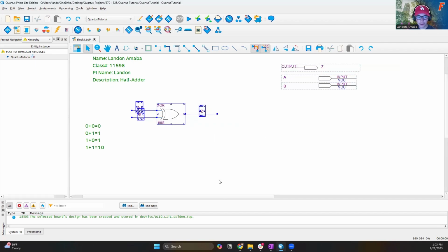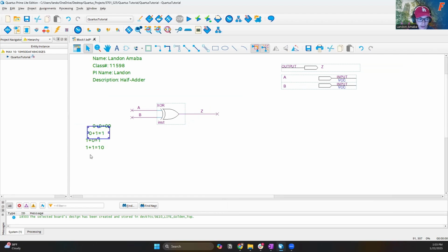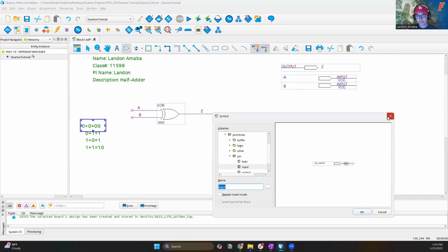We have our exclusive OR gate. This will handle the first 3 operations, 0 0, 0 1, and 1 0. But then how do we specify that there's going to be a carry here? In all these other examples, this is really 0 0. This is really like 0 1. This is really 0 1. We can look at the pattern and notice that every other second place right here will be a 0, except for this one. That's another familiar truth table, which is our AND gate.